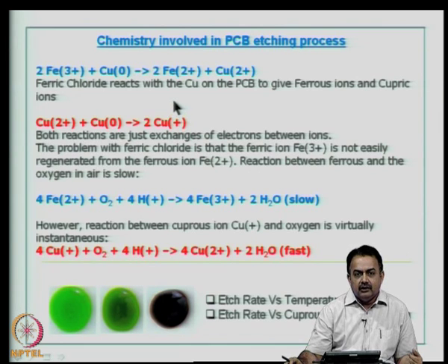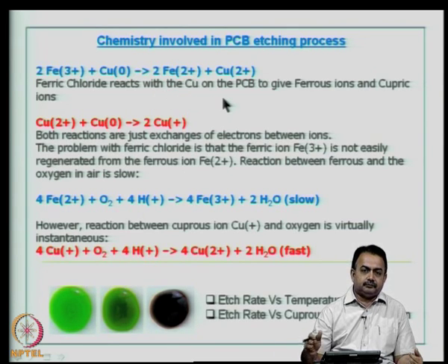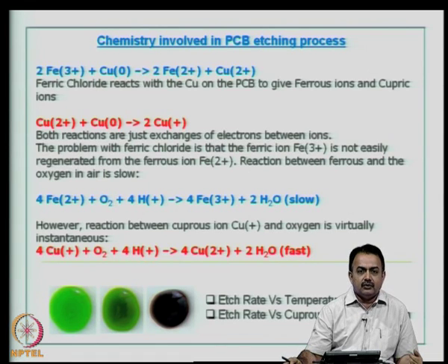And also if you look at the recycling process for ferric chloride and cupric chloride, in the spent ferric chloride etchant you have Fe2+ and Cu2+. Therefore, the removal of Cu2+, which is a commodity that is worth removing from such a spent etchant, is going to be very complex, whereas in this case where you have only copper, it is going to be recovered fairly straightforwardly.